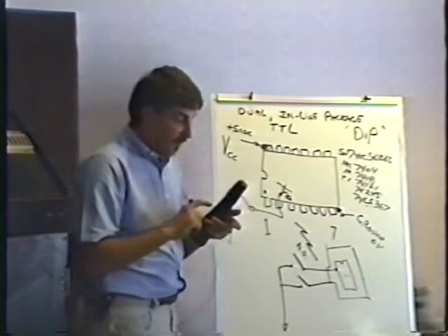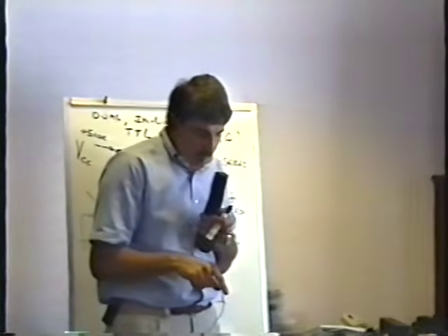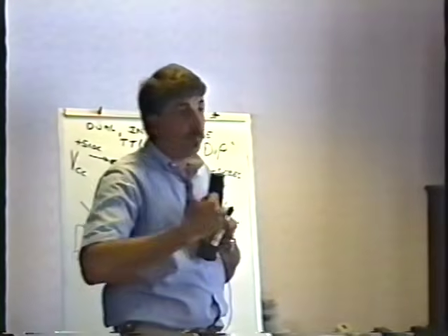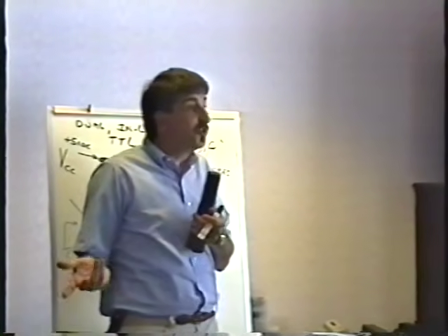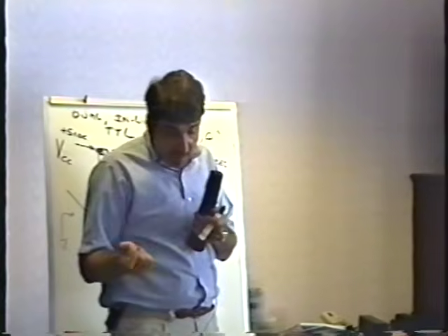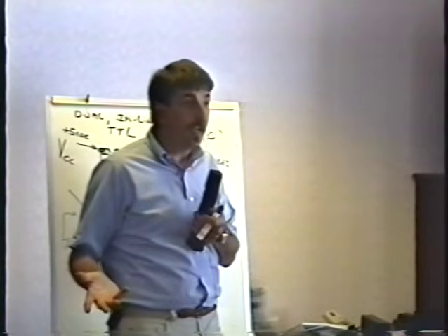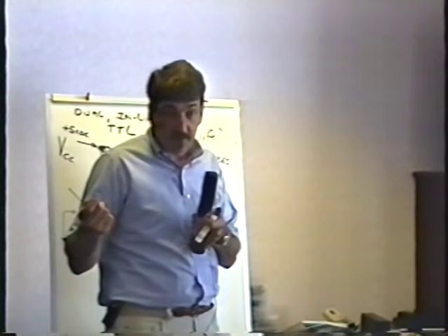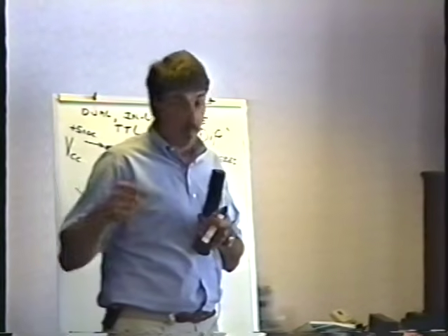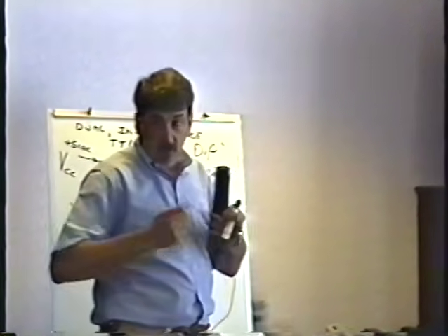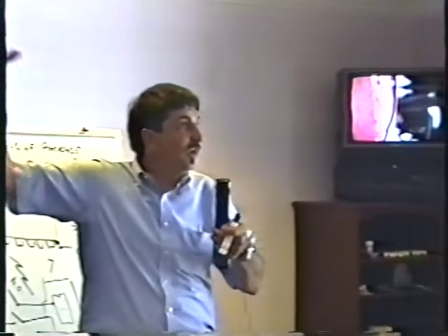The symptom that you get is this. Maybe you've seen this. You coin up the game, and you press the start button, and the guy starts to move right by himself, or left, or up, or down. And so you go, well, that's easy. It's a joystick problem, right? So you open up the control panel, you examine the switch for move right, looks perfect. You meter it, it meters perfect. You take the wire off, let the wire hang in the air, you try coining it up, it still moves right by himself, with the wire hanging off. So you hold the wires this far apart thinking that the air is conducting or something like that. You don't know what's going on, still does it.